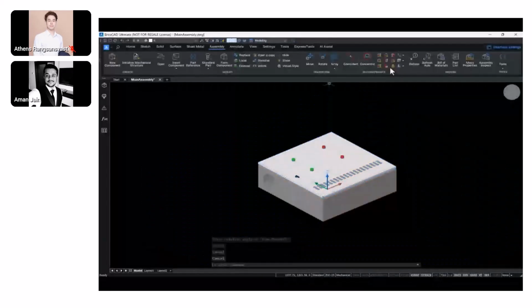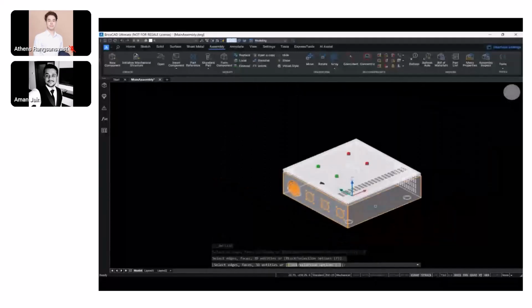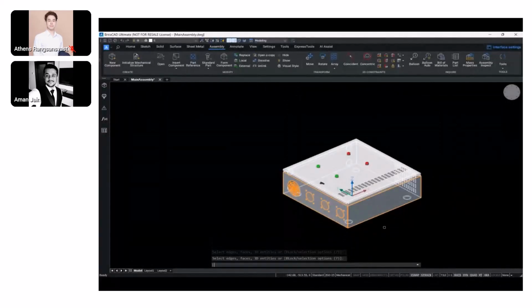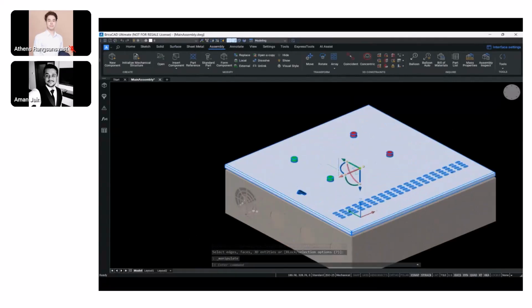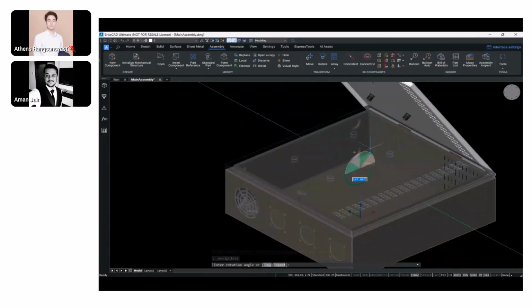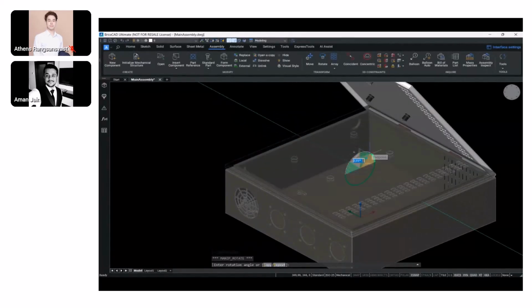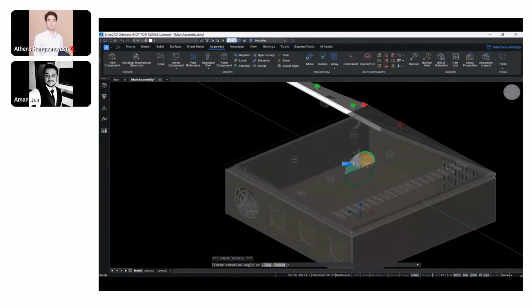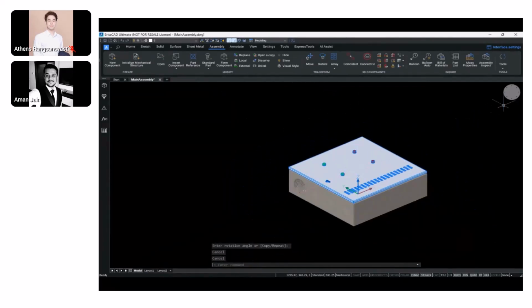So we'll fix the body, right? Because it's translating in the x-axis, we'll fix one or both of these faces once again, so that now when I'm trying to rotate the door across the hinges, across this particular axis, okay, now it's steady. So now I can see the body does not translate when I'm trying to rotate the door, and it's perfectly mated. So this now completes our assembly.